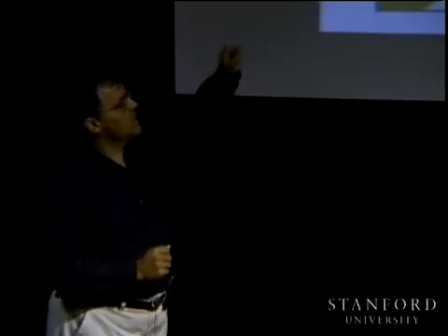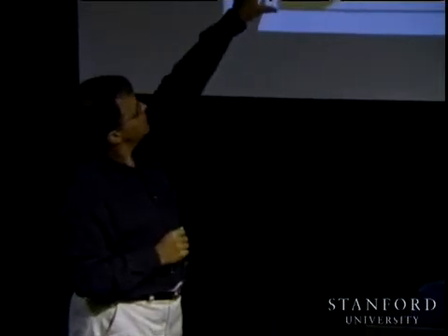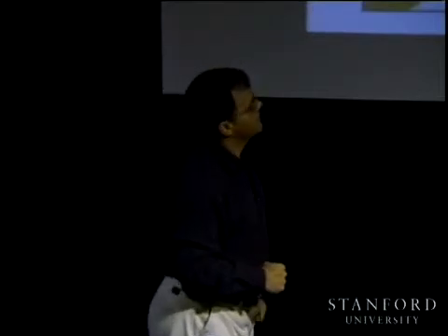And so then we just have to plan a path for one point in that space, which can be done many different ways geometrically. These grown obstacles are called C-space, configuration space obstacles, and this is a C-space planning approach.